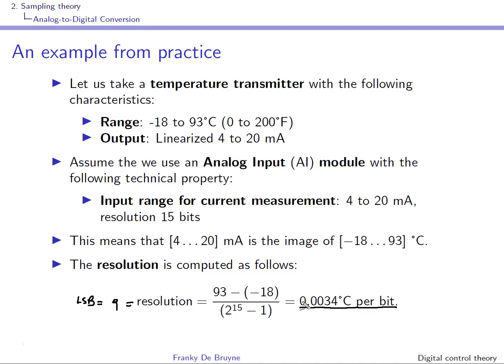And remember also that the quantization error varies between plus minus the least significant bit divided by 2.